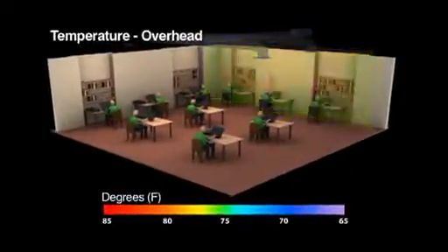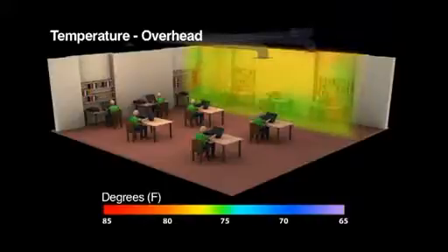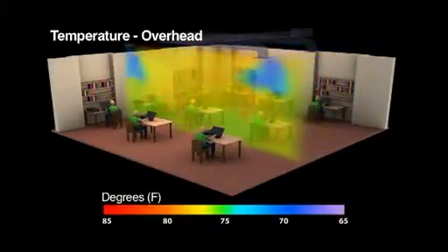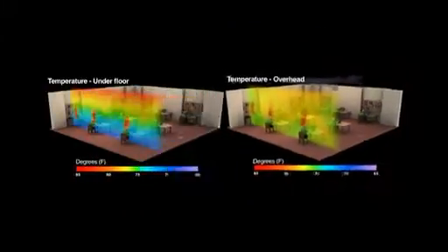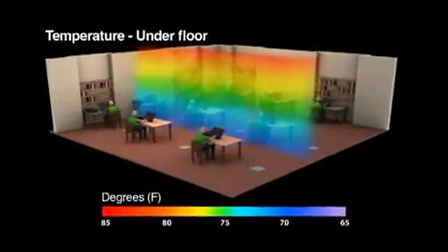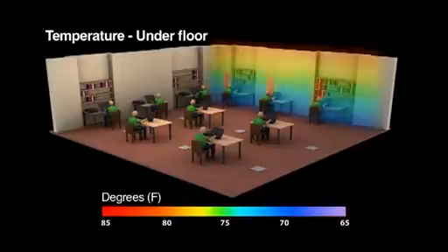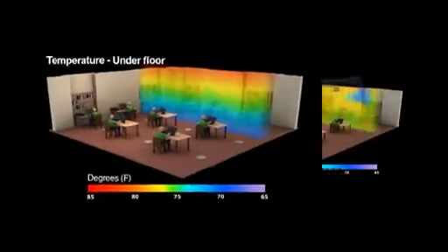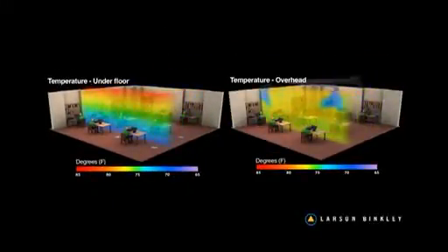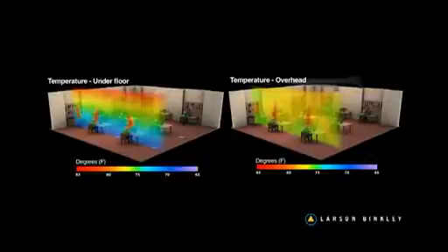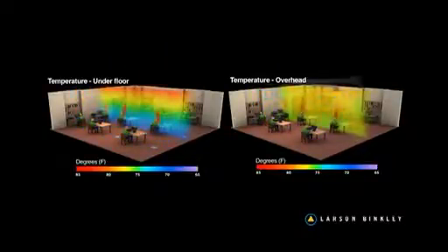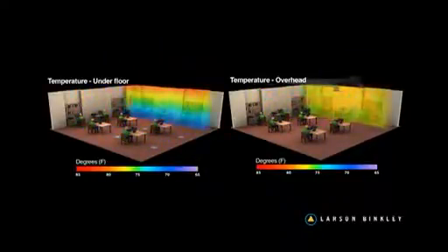The mixing system is doing what it was designed to do, constantly mixing up the heat and contaminants in the space. The underfloor air system is allowing heat to stratify in the unoccupied zone, shown as a redder color toward the ceiling. You can see the heat plumes are more pronounced on the underfloor side of the profile, and that the conditioned air is more concentrated where the people are in the space.